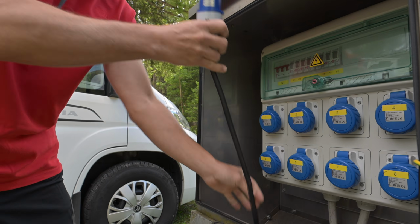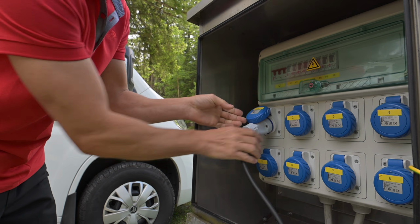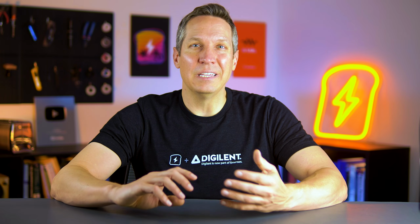Every real power source, such as a battery, generator, or power supply, has some internal resistance. It may be small, but it's always there. This internal resistance means that some of the source's voltage is dropped inside the source itself before it even reaches the load. That's why a flashlight gets dimmer as the battery drains, even when the measured voltage still looks decent.